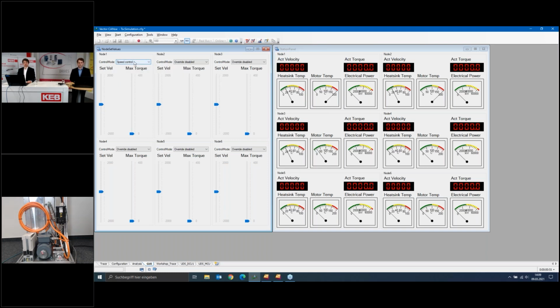I will now set my first node to speed control. This will change the CAN telegram that is sent to the T6, and it's already starting up, as you can see in the camera. And I just want to repeat, the MCU is in default state. I did not change anything. I just used the default setup, and the inverter is directly ready to go. Of course, the inverter needs information about the motor, but this is already prepared in this case. But the MCU is in delivery state and, if you use the torque speed control app, it's pretty easy to get the first reaction of the drive.